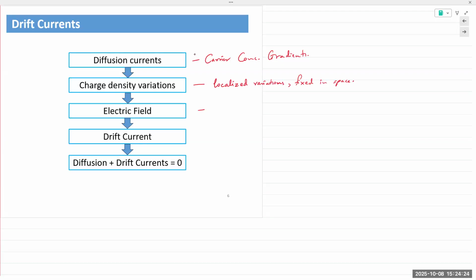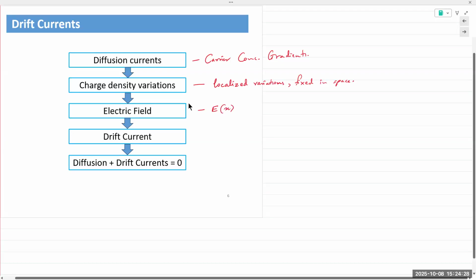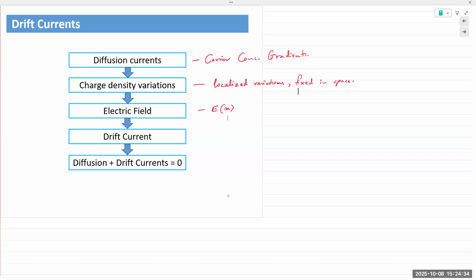And so we represent this as E of X. X simply notes the distance into the N and P type material. Okay, X-axis, literally, that's what it means. So it's the electric field, how far into the junction it extends. Okay. In the N type, we refer to it as Xn, and in the P type, Xp. Put together is the size of the junction.